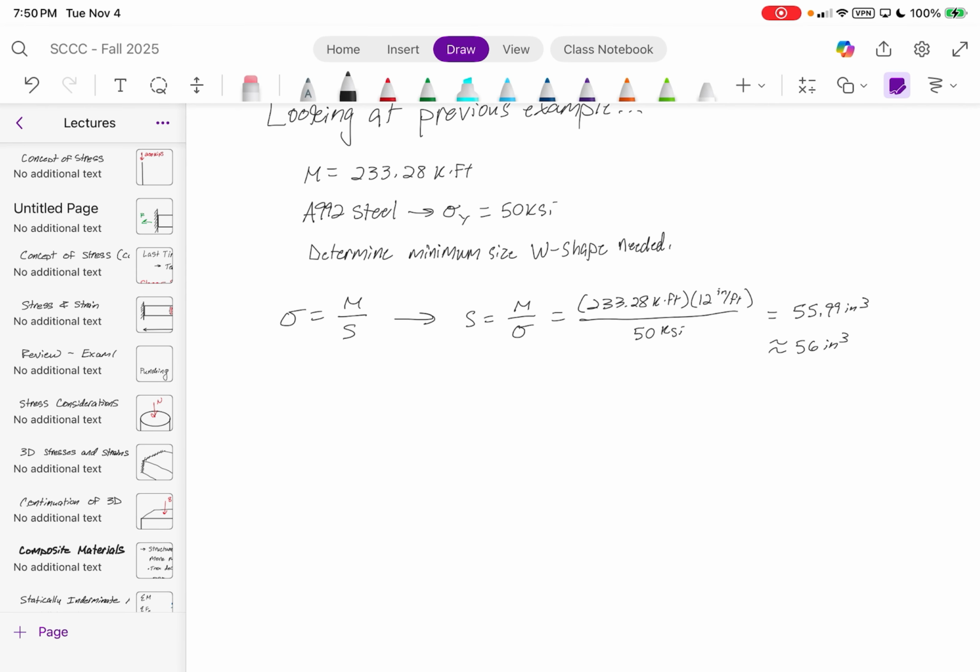you would use it if your W shape was basically being installed like this. Do you want your W shapes to be installed like that? Absolutely not. In very rare circumstances are they installed like this. The only thing that immediately comes to mind is lagging for retaining walls, and then generally you might have some type of strut here. But other than that, no.